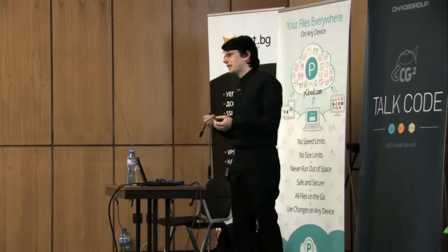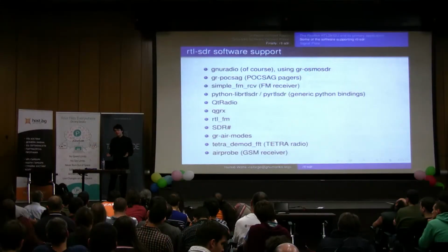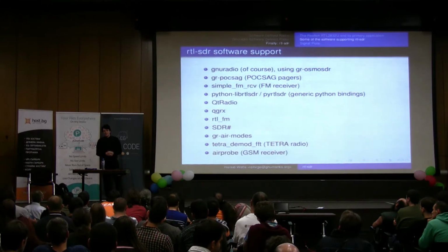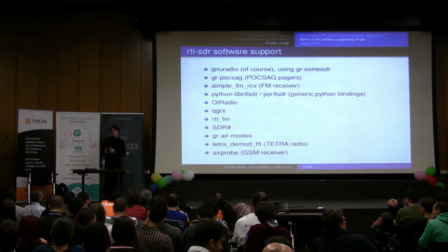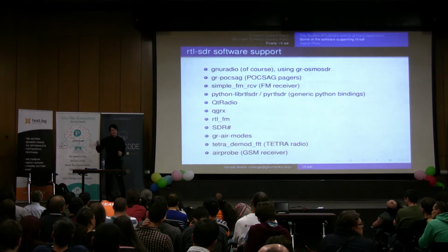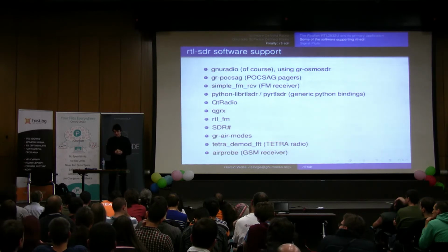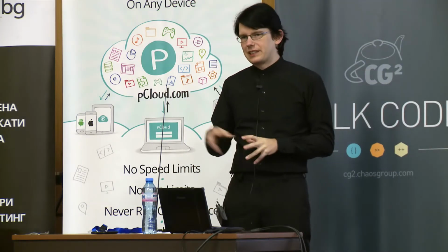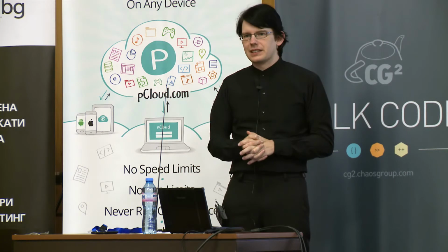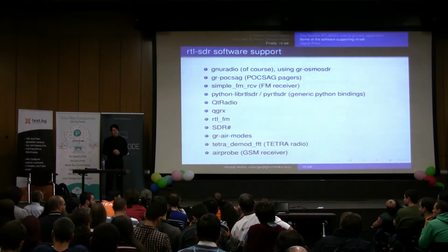Because if you have long coaxial cables, they have lots of losses, or the cables have to be very thick and sort of not very easy to install and so on. But putting the receiver directly at the antenna and then forwarding digital samples over Ethernet is, of course, a very nice solution to this problem of directly capturing at the source and avoiding any antenna cable losses. Questions?